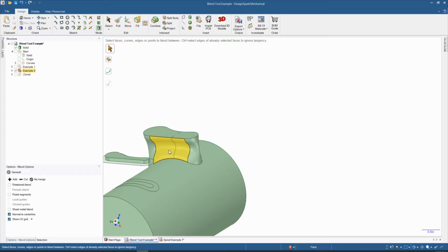So I have one last thing to show you. Sometimes blending from one surface to another becomes very difficult. Let me show you this example. If I wanted to blend this surface to this surface and have it be a semicircle, I have one more guide I can turn on here. So that shows you the path that I want it to take.